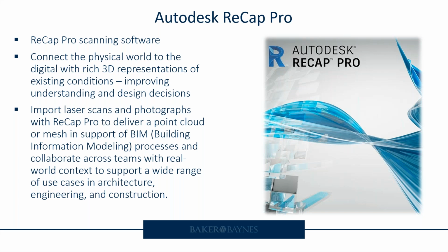For those that are not familiar with it, Autodesk ReCap Pro is used for the point cloud processing and registration. So you would bring in the point cloud, you would register it. If it's not pre-registered, you could do it via automatic registration or manual registration, and then create an RCP file or a structured scan, which can then be imported into your Civil 3Ds, your AutoCAD, your Revits, your Inventors. Okay, very, very powerful. It's used for as-built capture, and it's far much more automated than manual tape measure.